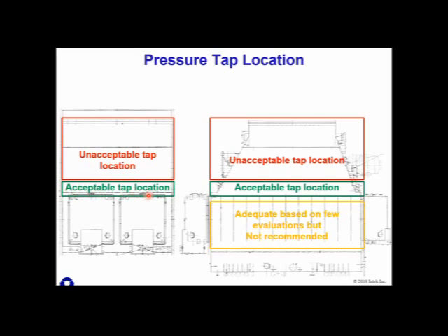So it really is of value to either walk down the impulse lines or to look at a drawing to figure out what drains come in near those taps, because you really don't want it near any high velocity or high temperature drains. We have installed, and in special cases recommended to keep costs low, instrumentation down in here. It works very well, but you have to pay attention to, again, these measurements being near drains. You can get a very good measurement for performance monitoring in these regions, but there's a lot more things to take account of.